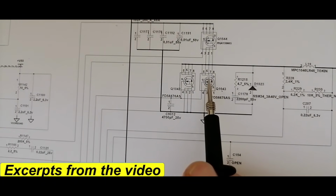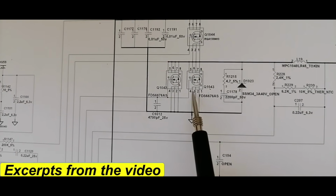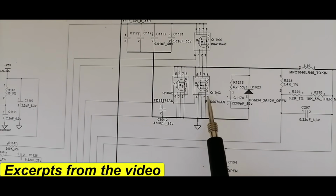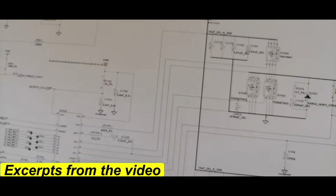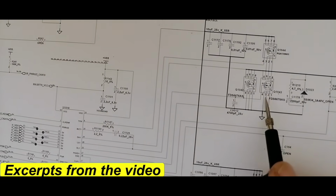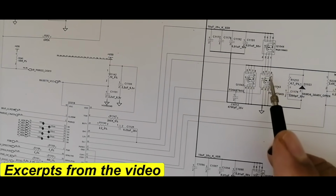As you can see here in the schematic, we have pin number 1, 2 and 3. These 3 pins are connected together. So this is the source. Do you see S? And the 4th pin is gate. The gate is always connected to a control IC. So 3 pins for source, the 4th pin is for gate, and the other 4 pins are for drain.